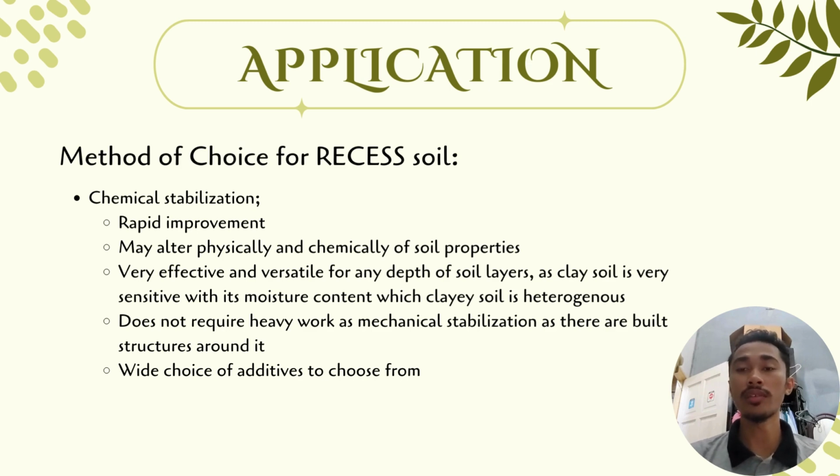But by choosing chemical stabilization, it is a safe option that is versatile, as we can choose which chemical we are going to use for the soil layers. It does not require heavy work, just like I mentioned. It does not require mechanical involvement in changing the physical properties of the soil, so it will not disturb the built structures around it. There is a wide choice of additives to choose from, just like I said just now. So chemical stabilization is the method we choose to apply in the recess soil case study. That's all from me. Thank you.